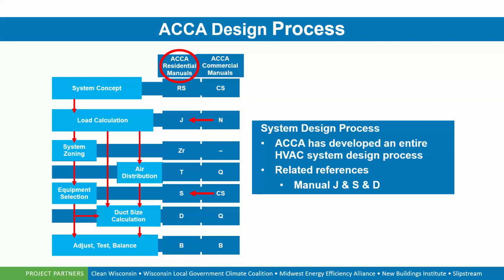And then finally, after we have our Manual J done, we have our Manual S. We know which furnace and air conditioner or outdoor unit, and indoor unit on the air conditioner or the heat pump, whatever the case may be. That's decided. We have our heat loss, heat gain for the building, and we have a required CFM from the design. We can then go on to the duct calculation. And that's a Manual D.